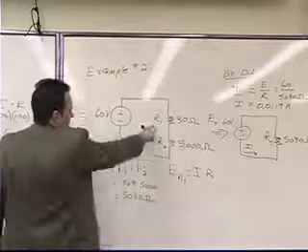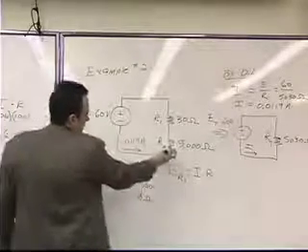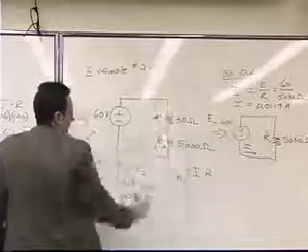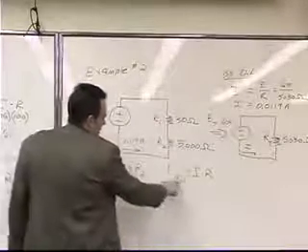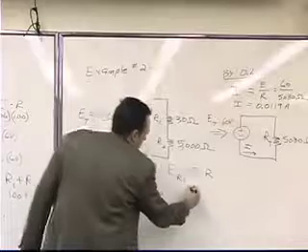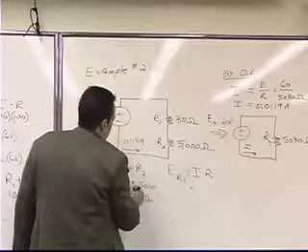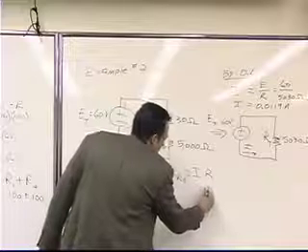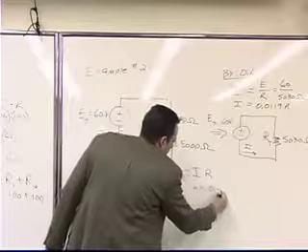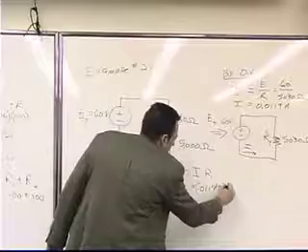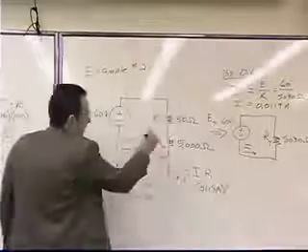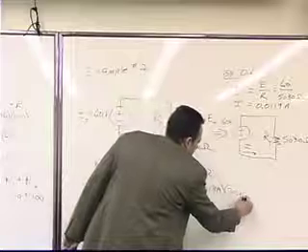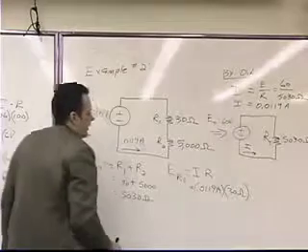So for resistor 1, because remember the currents are the same through both resistors, I'm just doing the top one first. The voltage drop on resistor 1 would be equal to 0.0119 amps multiplied by the resistance, which is 30 ohms. So what do we get for that?